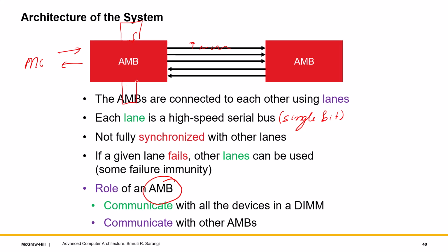But of course, this is a new memory architecture, and in general the memory community has not been very receptive to changes in the fundamental architecture, even though most FB-DIMM architectures try to be quite compatible with DDR. Again, it's not fully compatible with DDR, which is why this architecture did not fly, even though it's a great idea.